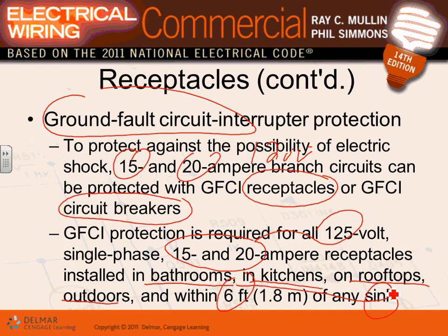Within 6 feet of any kitchen sink, countertop in a commercial kitchen, rooftop, anything outdoor, anything in a wet location, guys, is required to have GFCI protection.